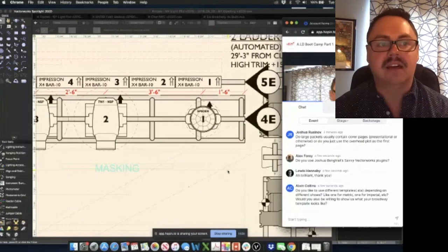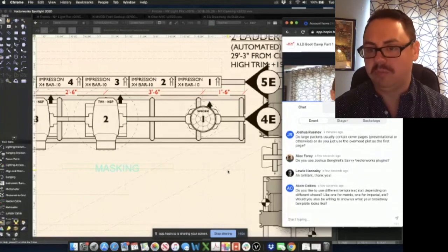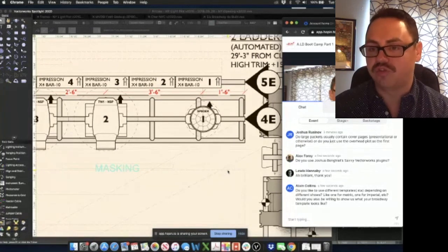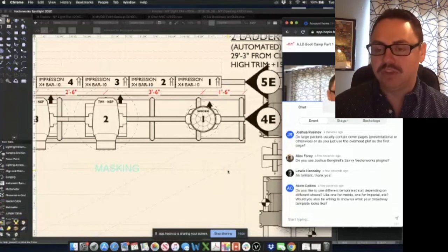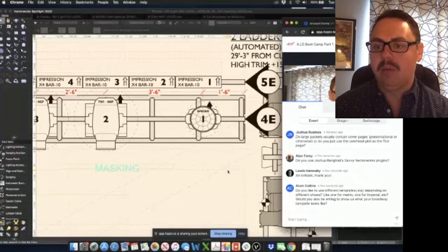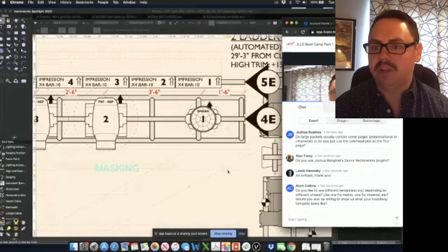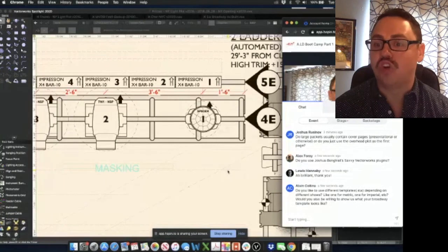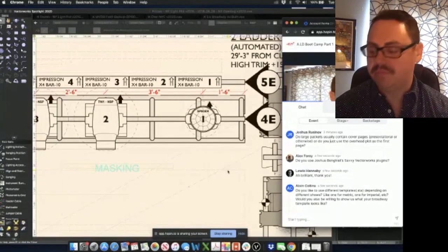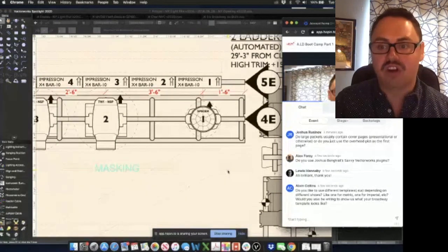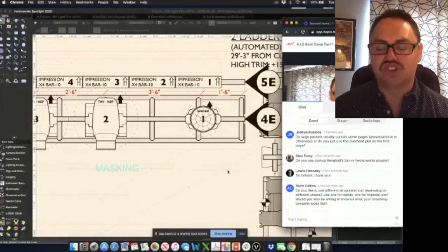In the settings of Vectorworks, you can change a drawing from metric to imperial, and it will do all the conversions for you. So, for example, when I'm using stuff from the UK, most of them draft in metric, and a lot of scenic packages I will be drafting metric. I know inches because I grew up in the United States, so I will take the metric, import it that way, and then switch over to inches and everything else in my drawing so that it's a language that I understand quickly.